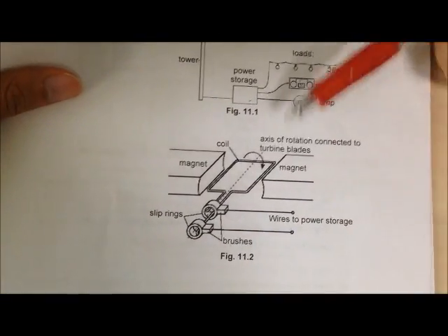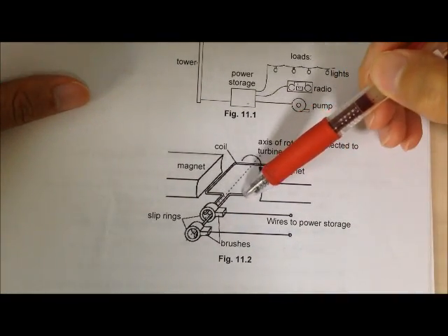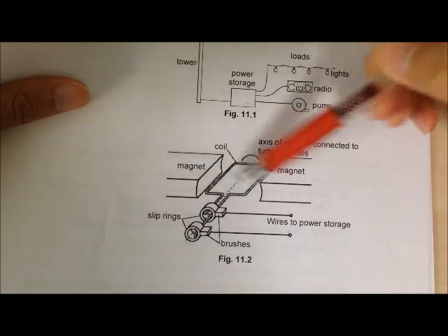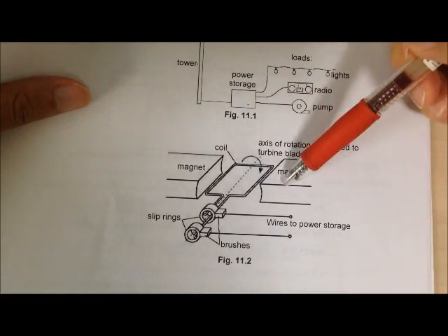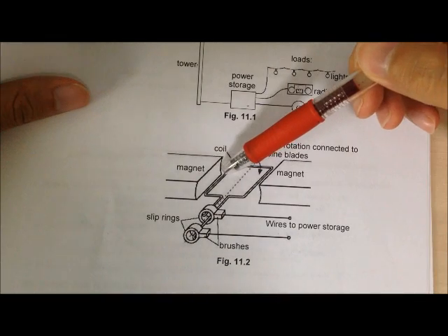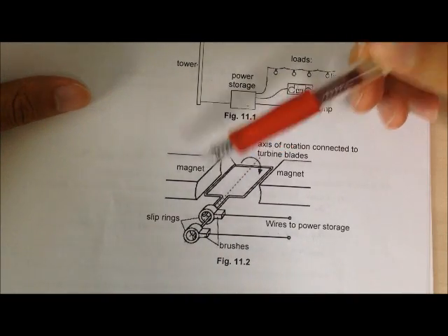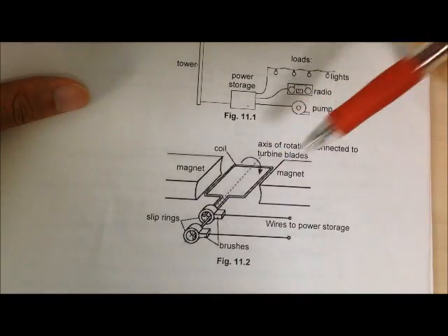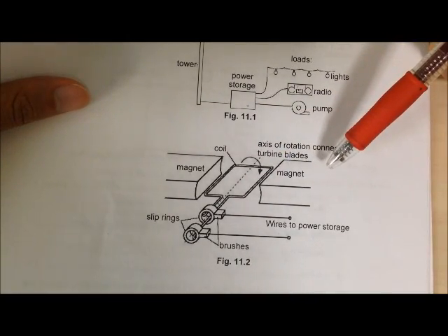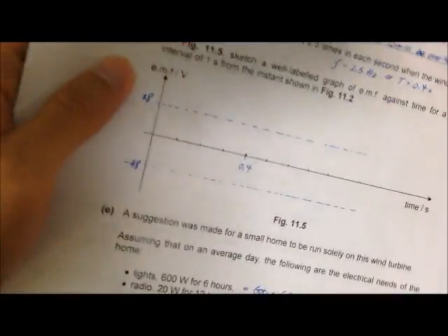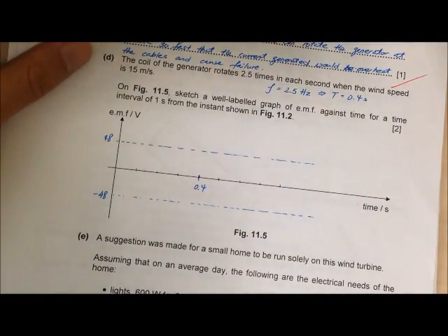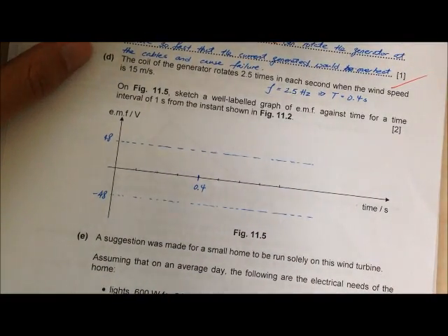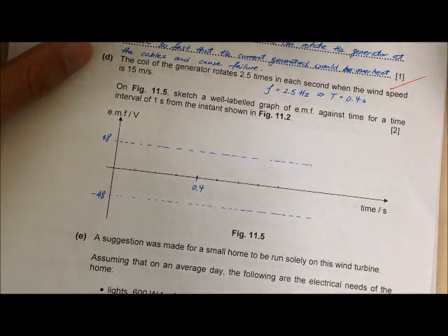So how do you find out the information? You need to read this diagram. From this diagram, you know that the starting position is the horizontal position, and the horizontal position is actually where the magnetic flux between the two magnets is the most dense. So any small movement by the coil, it will actually experience a high rate of change in terms of the magnetic flux strength. Okay, so once you have that understanding, you will realize that the horizontal position will give you the maximum rate of change in magnetic field. So therefore, there will be the maximum EMF.